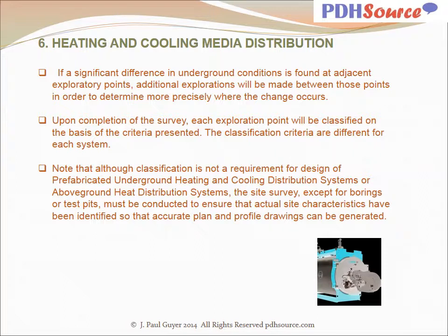Note that although classification is not a requirement for design of prefabricated underground heating and cooling distribution systems or above ground heat distribution systems, the site survey, except for boring or test pits, must be conducted to ensure that actual site conditions have been identified so that accurate plan and profile drawings can be generated.